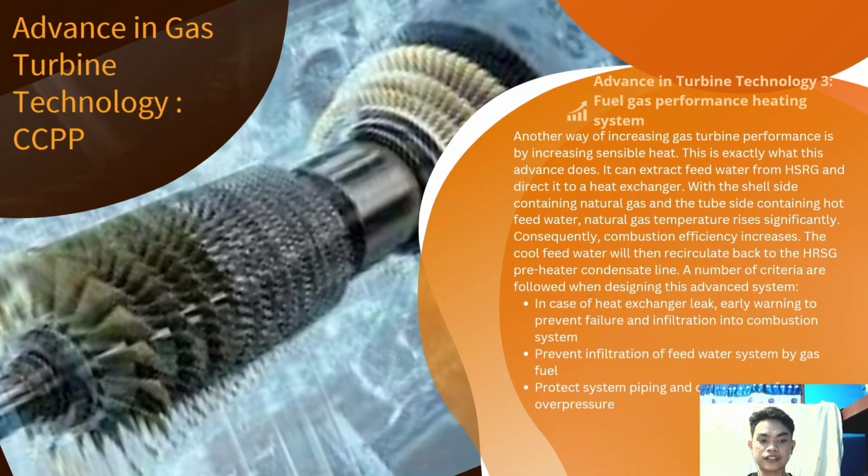A number of criteria are followed when designing this advanced system. First, in case of heat exchanger leak, there should be early warning to prevent failure and infiltration into the combustion system. Next, prevent infiltration of the feed water system by gas fuel, and protect system piping and components from overpressure.